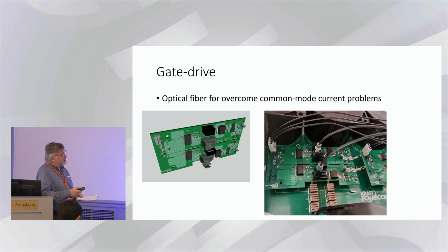At lower voltages, up to 500-600 volt, it worked fine, and at lower current, but when we were reaching 1 kilovolt and 600-700 amps, we disturbed the communication processor. We disturbed the electrical interface, so it was impossible to run the inverter.